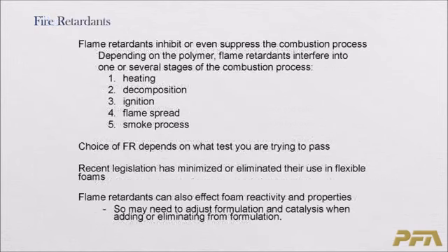Besides those solid fire retardant fillers, there are also liquid fire retardants. Again, there's a whole variety of different types out there, depending upon the type of foam test you want to try to pass. Let's say recent legislation changed some of the procedures, and the use of fire retardants in foams has significantly decreased. So just be cautious, like with fillers. If you're taking them out or putting them in a foam formulation, you probably will have to adjust the formulation to account for the acidity that was either there or would come in with the fire retardant.